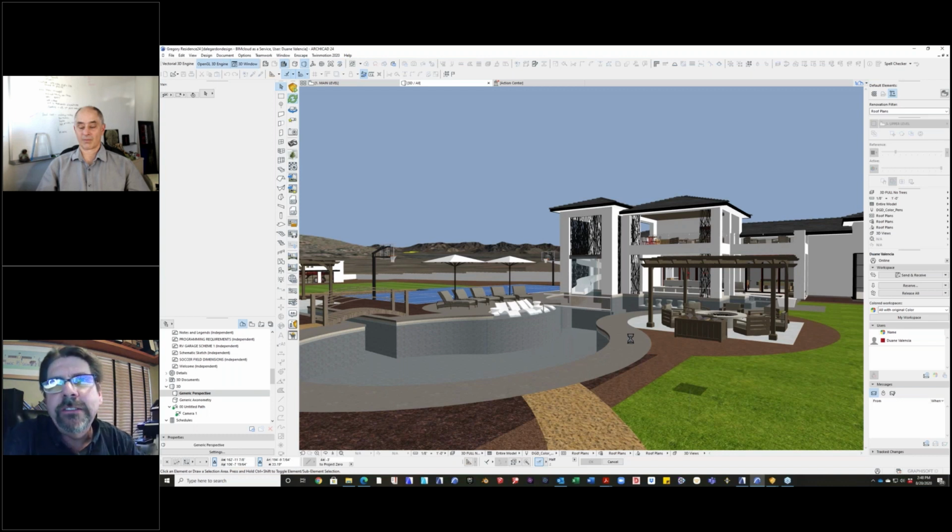Anyways, all the creation gets done in ArchiCAD and then it's manifested in 3D. One of the things you'll also notice is that Twinmotion does not use proxies, to my knowledge, so you're going to see everything as it should be. Enscape, however, uses proxies. So when I stick an Enscape object into an ArchiCAD 3D window, like I just did, it's a placeholder, essentially. It's not going to look like you want it in ArchiCAD.